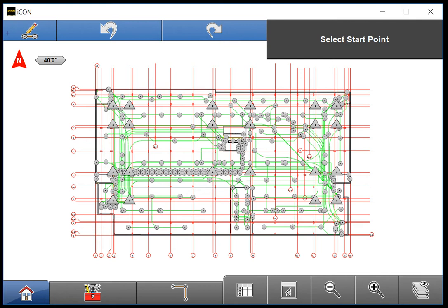If no CSV or DXF files appear in your Layer Manager, ensure that they have been properly loaded to the job associated with the floor you are working on, within the project you were working on, and that you are currently working in the correct project and job. If you touch lines in the background and nothing happens, make sure you have your data loaded as reference data and not background images. You may visit Video 7 for a refresher on project setup and organization.